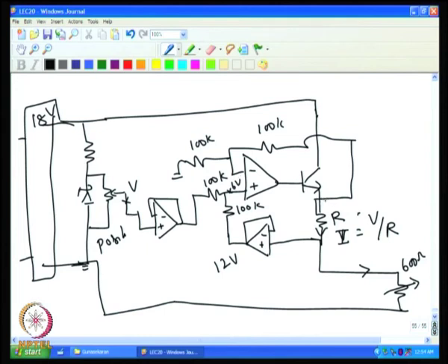But then whatever voltage is coming here also has to be equally divided by half. For example, for 0 current, if this is 0 volt, then this also will be 0 volt. If some extra voltage is there, half of that will come here, and whatever voltage is here, half of that also has to come. If this ratio is not equal to this ratio, then the difference is not correctly reproduced at this end. So, we have to make sure that this ratio and this ratio are equal.